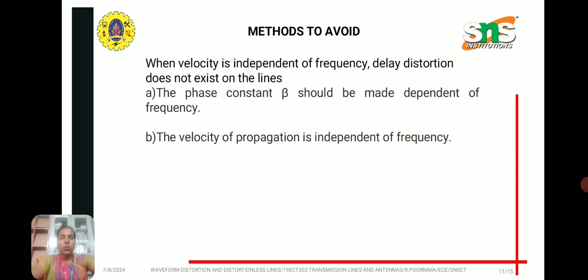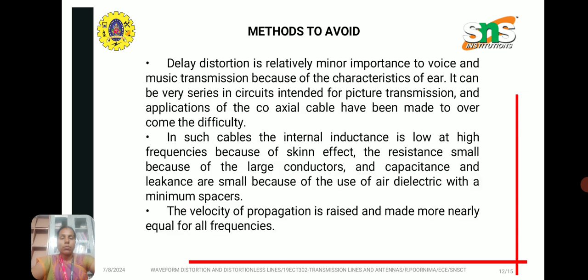Methods to avoid the delay distortion. The phase constant should be made dependent on the frequency, and the velocity of propagation should be independent of frequency. Delay distortion is of relatively minor importance to voice and music transmission because of the characteristics of the ear. It can be very serious in circuits intended for picture transmission.